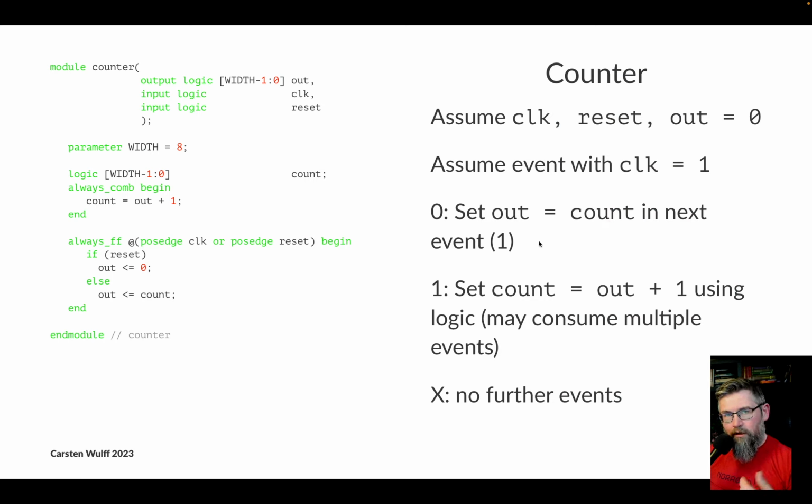Now, that might be quite fast, or we might actually model the delay of the D flip-flop. So this is where timing can come in. You can either add that timing to the Verilog, or you can use a Liberty file to describe that timing.